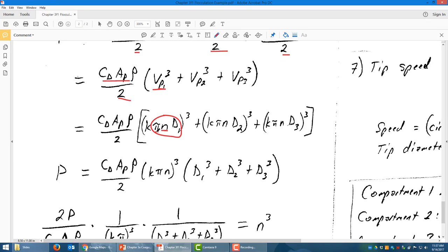And the circumference is pi times the diameter. So, for example, if I had a 1 meter diameter circle, then pi times the diameter would be 3.14. That would be, the circle is traveling a distance of 3.14 meters around. So that's the distance, and with the angular velocity, sort of the number of rotations per time, then I can calculate how fast this thing is traveling in a meters per second speed term.